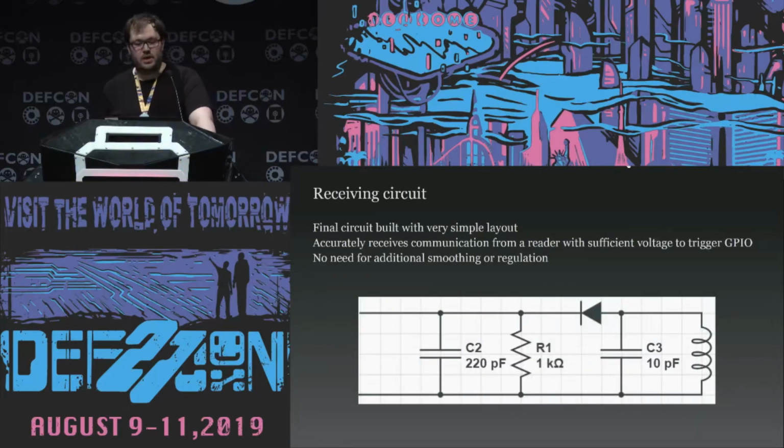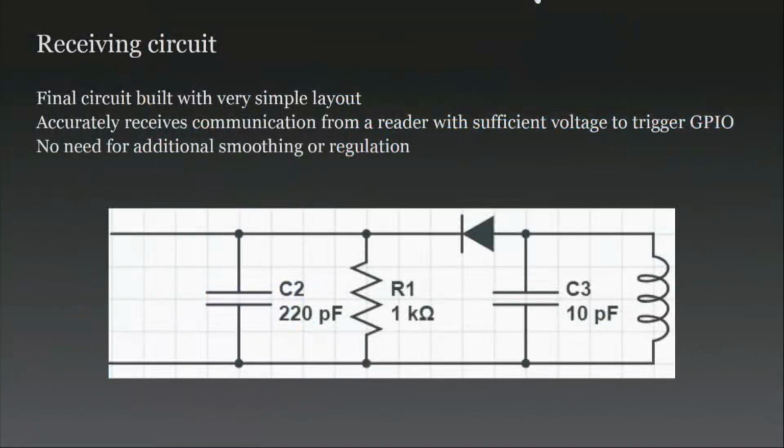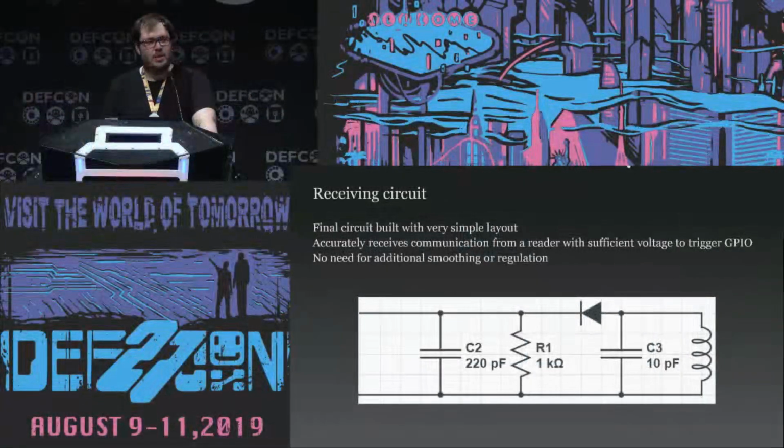So that's the full circuit that you need to use in order to connect a microcontroller onto the NFC technologies that are being used. Now, I don't often draw circuits, so it's not perfect, but it does seem to work. I would then tie one pin to a GPIO input, and then that same pin to a GPIO output in order to modulate on the power being received, and then just to the ground on the other one.